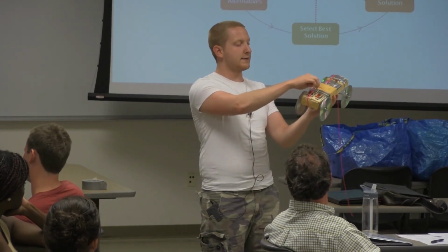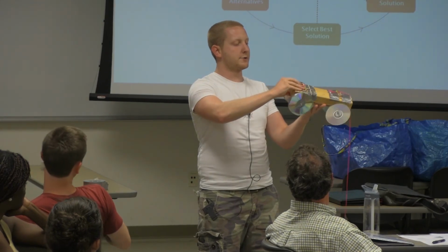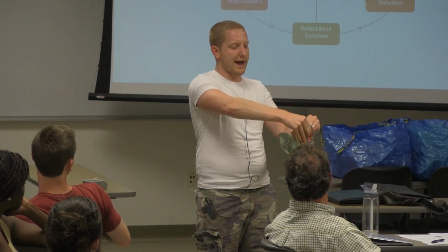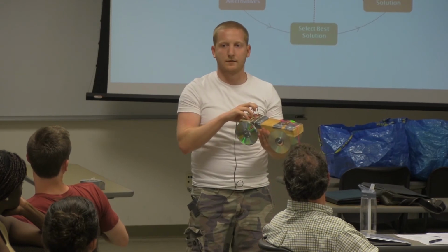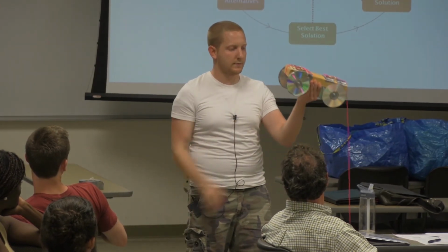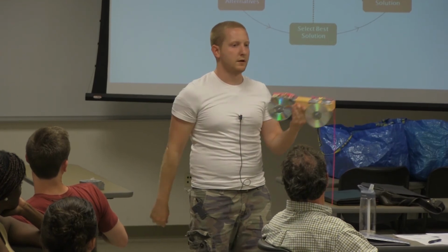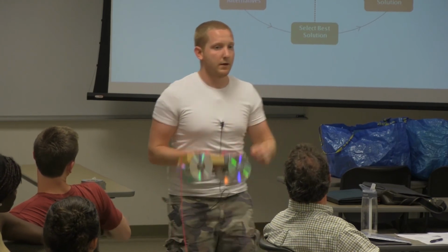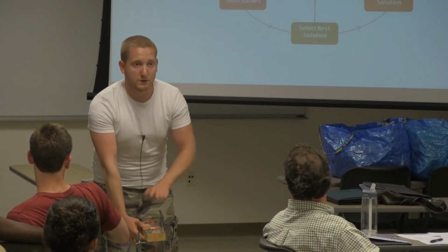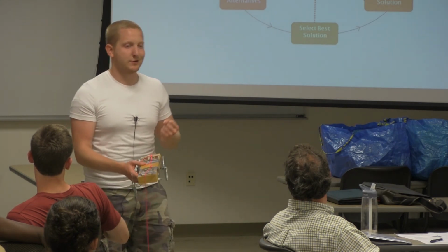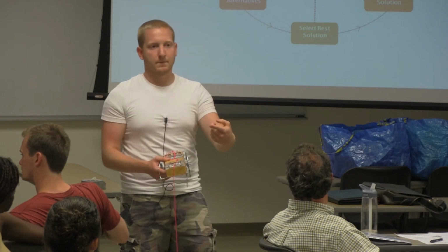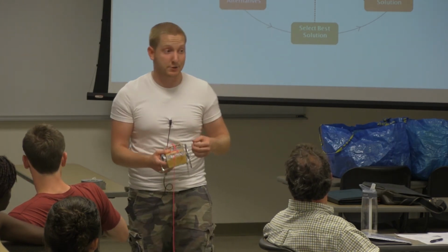All you do, you take this string, you bend your mousetrap backwards, and then you spin your axle around. It tightens, and then when you let your mousetrap go, guess what it pulls? The string and the rubber band and your axle. And it keeps the back parts of these moving, and it'll actually pull your car along. Now, if you were to just use string and put this on the ground, the wood's too heavy. It won't go. If you use the rubber band, it adds that extra oomph to it, and it keeps it moving. All right, that elasticity in the rubber band actually makes it go far.